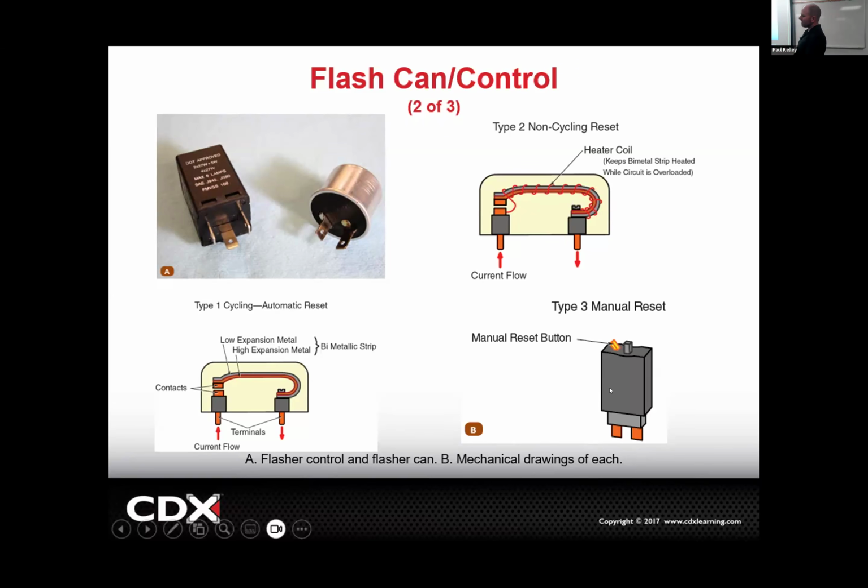So even on a newer car, if you jump in and you turn the left turn signal on, it flashes fast. It's because the body control module is checking how much resistance is in each of the bulbs or monitoring voltage drop, and it knows the bulb is out. So a lot of the cars will make it flash fast artificially just to prompt you to get it fixed. Some cars will actually give you a warning light saying, hey, you have a bulb out, and it might flash normally. It's kind of interesting.